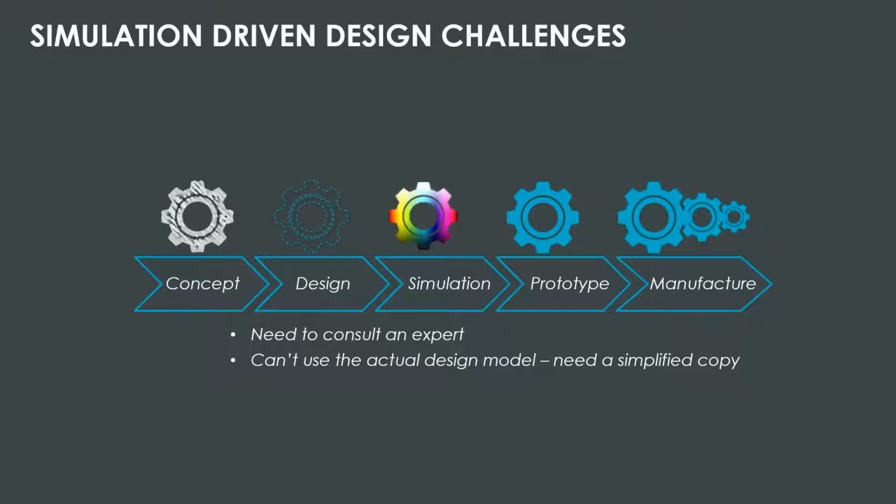Some of you that have done finite element analysis, the traditional finite element analysis process, right? Regardless of the complexity of the part or the assembly or the design, you will have to defeature it so you make it analysis ready. Many times we would have to spend some time getting rid of unwanted features, so that the mesh size gets lesser, so computationally it becomes less expensive. So it's almost like you make a copy of it or do a save as, and then you go from there, right? And typically engineers don't feel comfortable making that judgment, even when they are working with these copies.